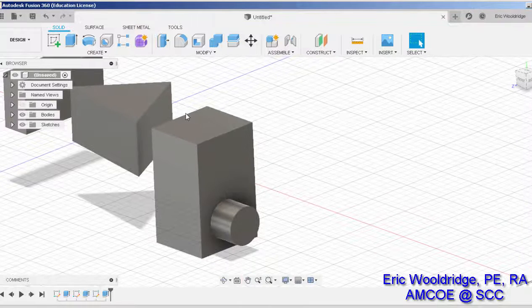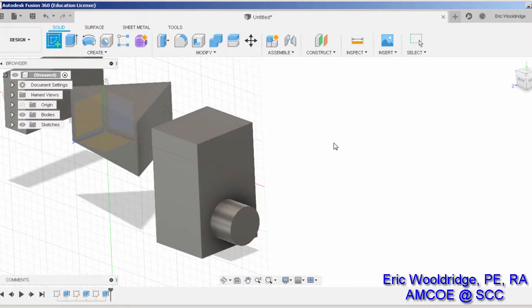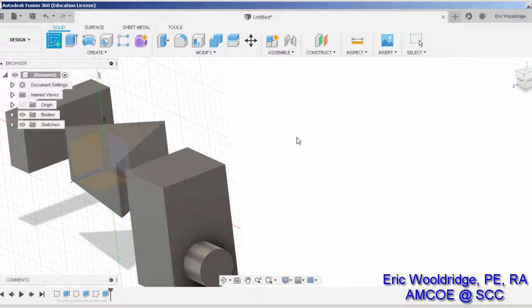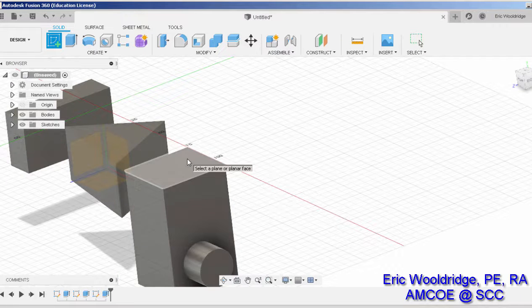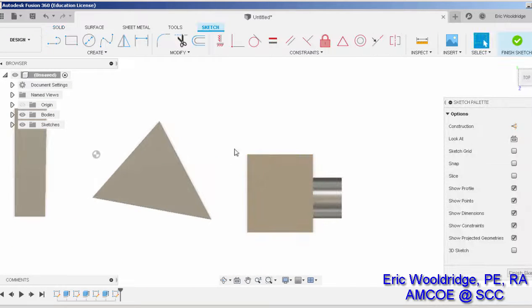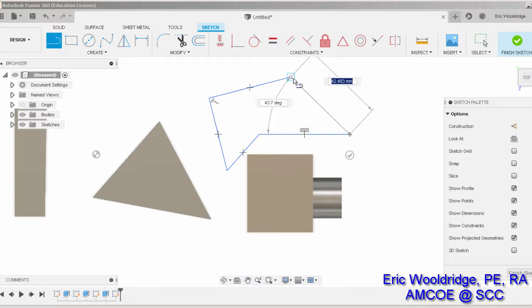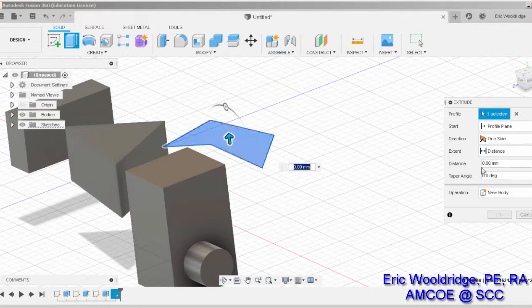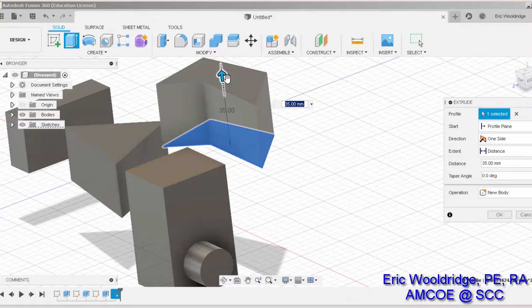Alright, let's do another one. Create a sketch. This time I'm just going to click, I don't know, maybe on top of this surface, or I can actually just click out in space too, doesn't really matter. We're just sketching along. So I'll click right here, and I'm going to draw maybe something with a few more edges, something a little bit less triangle or rectangle. Notice that when I come back, I always hit my start point so that it closes, and also notice that it becomes a sort of a shaded in space. After that's done, I hit escape, finish sketch, and hit my extrude button, click, and I can type in a value here or just grab my little arrow and pull it up and say OK.